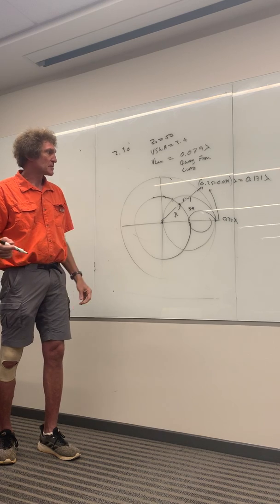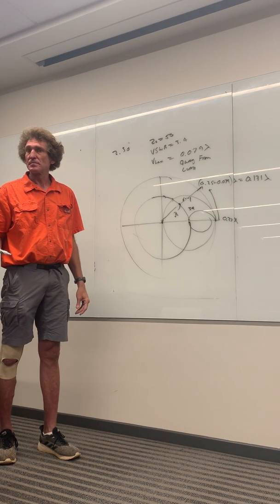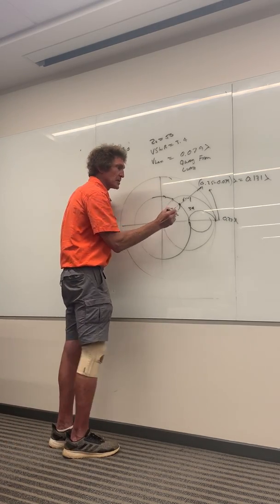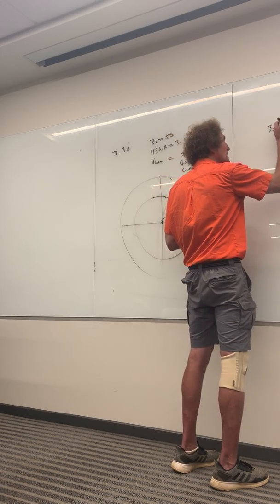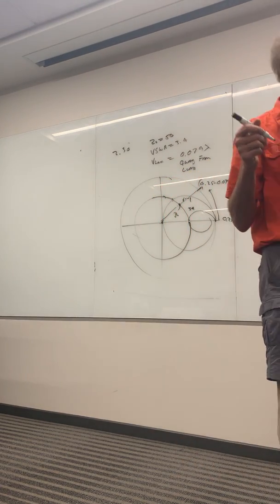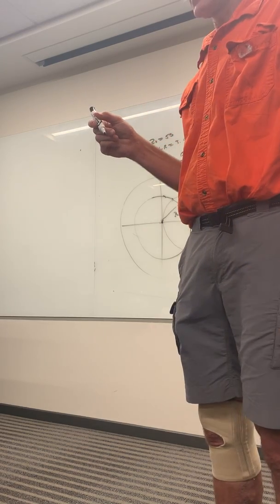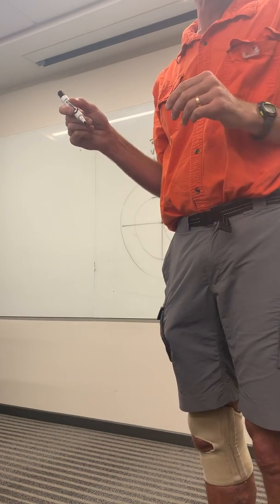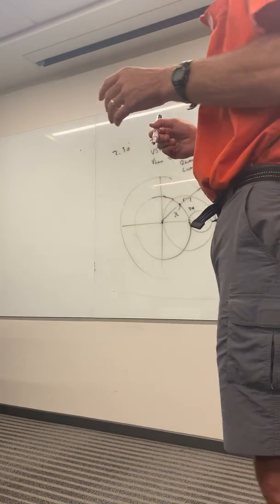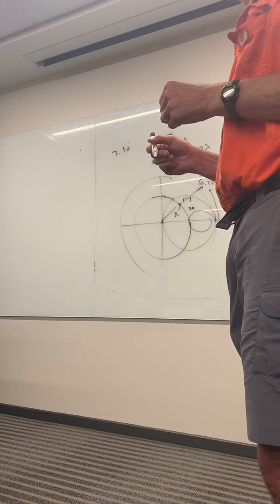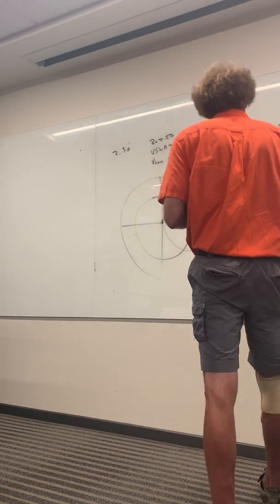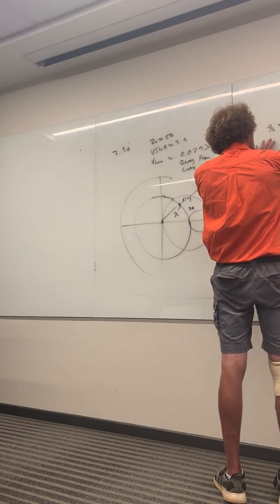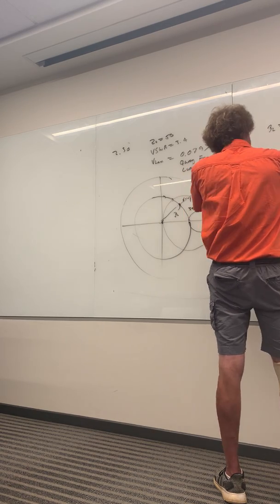Now, what else is the question asking for? Determine the load. All right. Can somebody look here and tell me what ZL is right there? The normalized value of ZL? Do it on your Smith charts, because the more you work with them, the better you remember how to work with them. What did you get? Is it roughly 1 plus J 1.3? Roughly. Is anybody else getting that? So it's right on the one circle, right?